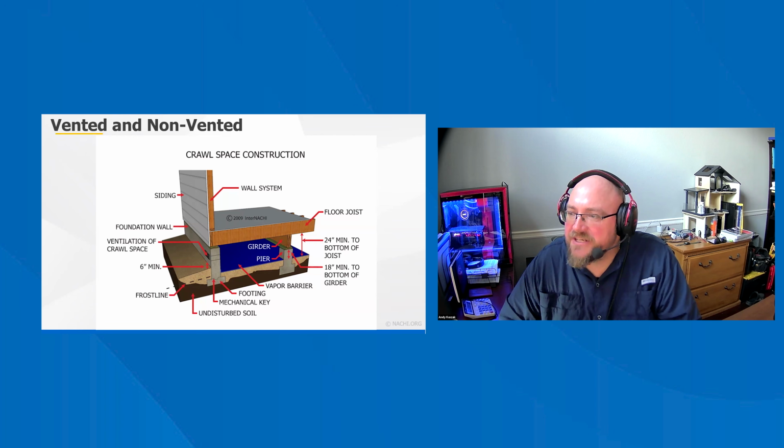The principal disadvantages of a vented crawl space: pipes and ducts must be insulated against heat loss and freezing. A larger area usually must be insulated, which may increase the cost. And in some climates, warm, humid air circulated into the cool crawl space can actually cause excessive moisture levels in wood.